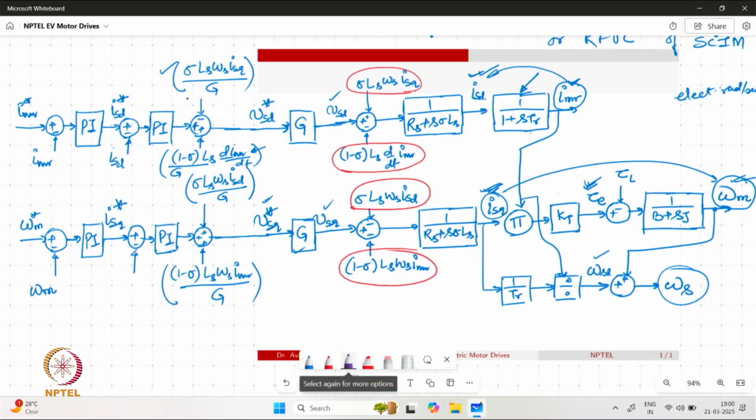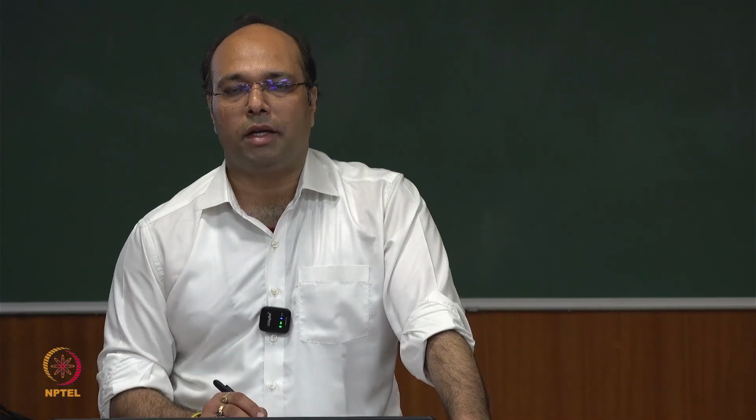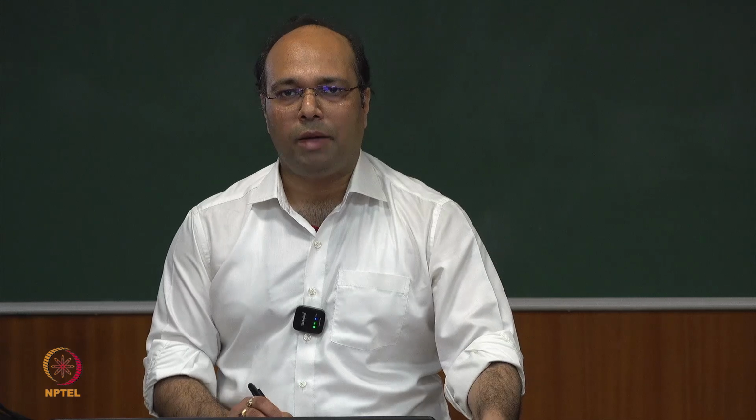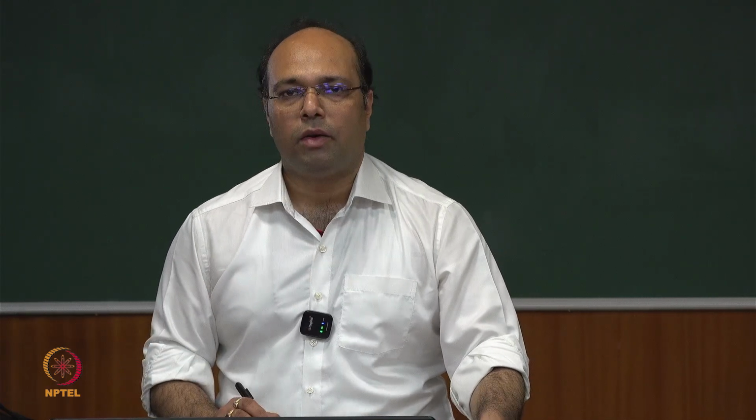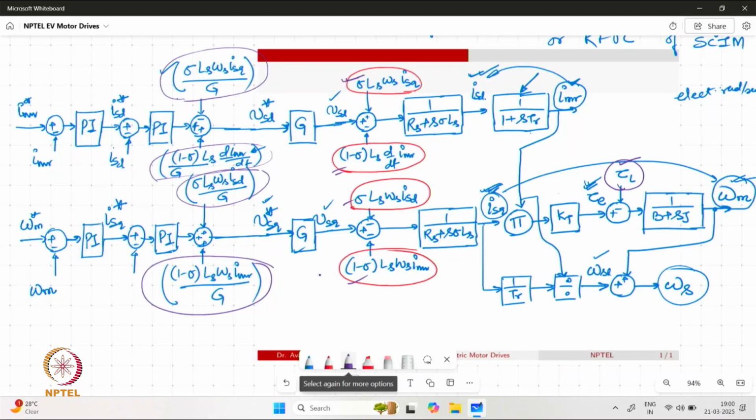For example, all the feed forward terms which are cancelling the nonlinear terms can be considered as the disturbance to the system. Similarly, the load torque which is applied on the system, which is not internally controlled or not internally generated, is an external force, external torque. So many a times the estimate for this is not available, so it can be treated as noise or disturbance to the system.